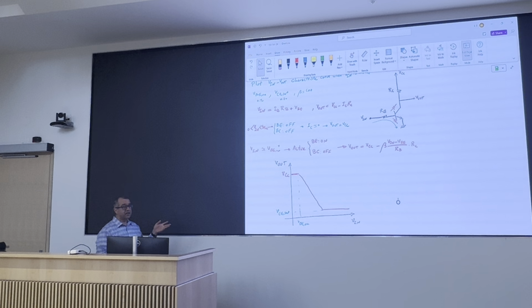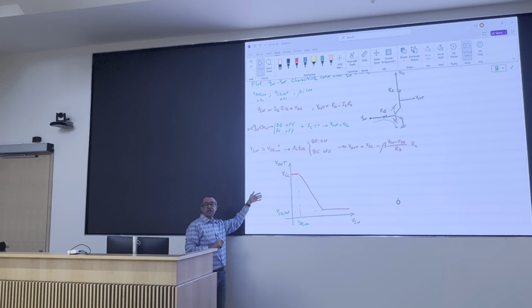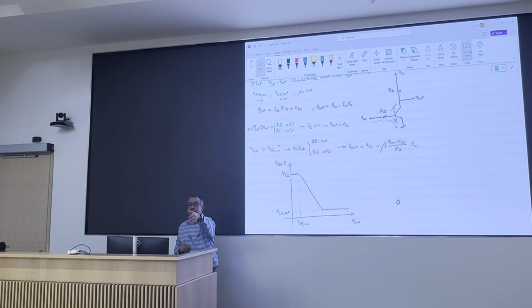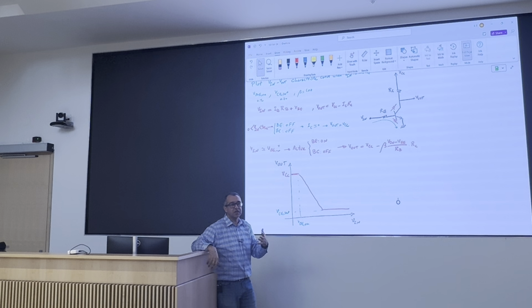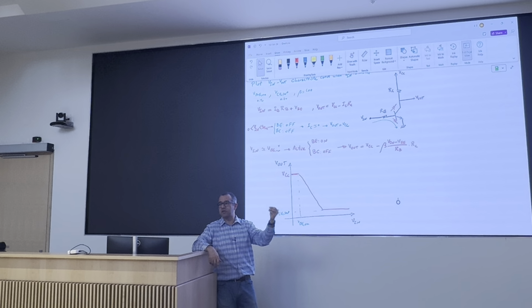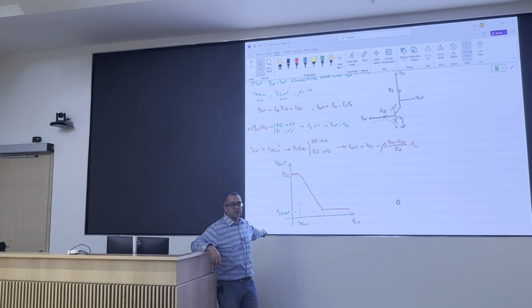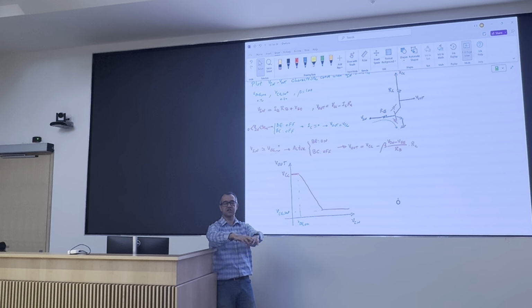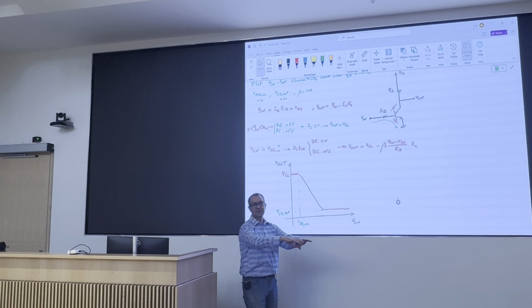So already it does something I haven't seen before, and it does something useful as well. With diodes, you can make AND gates and OR gates. You could never make an inverter with diodes. Now you can make an inverter. You can make any logic circuit that you want, any CPU that you want, with a bunch of diodes and a few transistors. Done. This is where the digital people start. They didn't progress after.